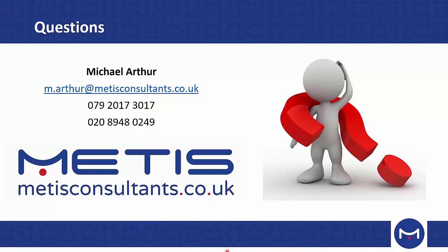Thank you. I think your answer covers a few more questions where people were asking how you verified the LiDAR data and accuracy. So you just did say that you tried to use as much as you could the Thames Water data and the manhole levels. What return periods have you used, and what was the percentage of climate change you applied?